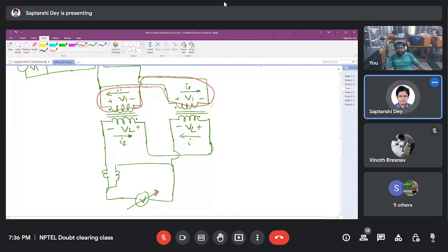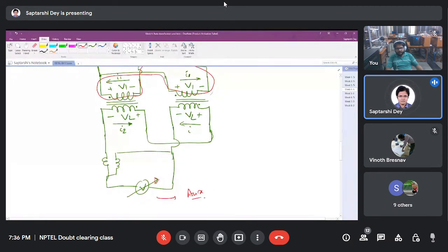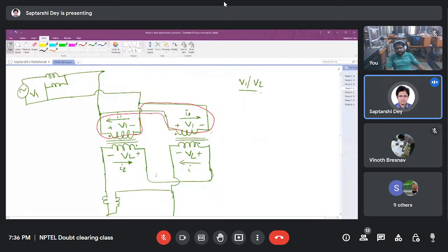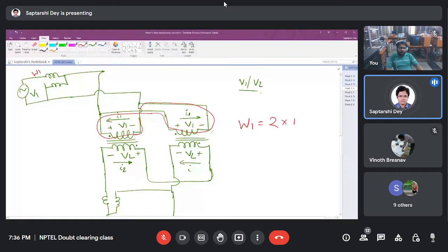So they are also not drawing much power. Now, before connecting this supply voltage, which is sometimes called the auxiliary supply, we had these terminals open. So this wattmeter W1 measures 2 times the core loss.